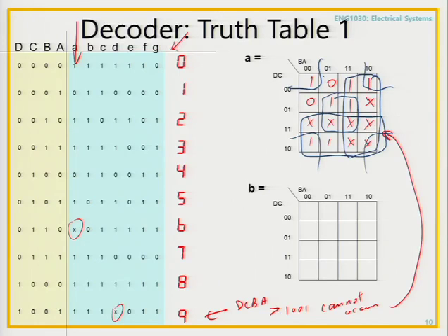So good practice would say that you should design for what should happen on the output, even if you don't expect to get those inputs. Anything greater than that, you should still design that. Like say all zeros or something. Yep, so you could set it up so that anything out of range, the display goes blank, for instance. Then you could set everything to 0. Okay, so that would be good design practice.